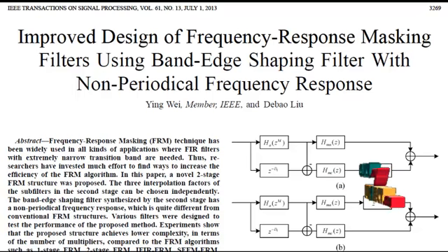So, the drawback of the FIR filter is overcome by the frequency response masking technique. In this technique, first of all, the filter is interpolated to get the transition band. Then the interpolated filter and its complement are masked. Finally, the result is obtained by combining all these together. This leads to low arithmetic complexity.